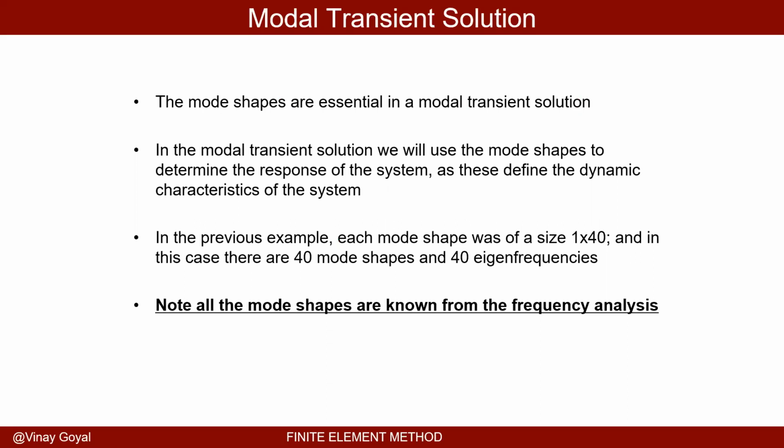So in the modal transient solution, we'll use the mode shapes to determine the response of the system, as these define the dynamic characteristics of the system. So what we're saying is that the mode shapes are the pillars, the foundation of how the structures deform. If I can determine what those fundamental motions are, then I can perhaps linearly superimpose them, by superposition, and then determine the dynamic behavior of the system when loads are applied.